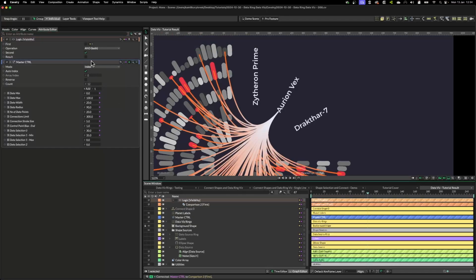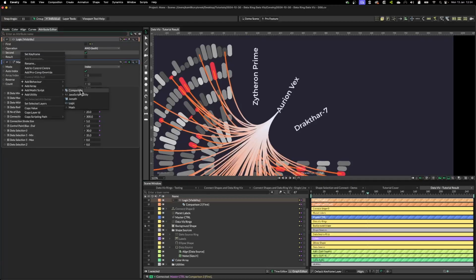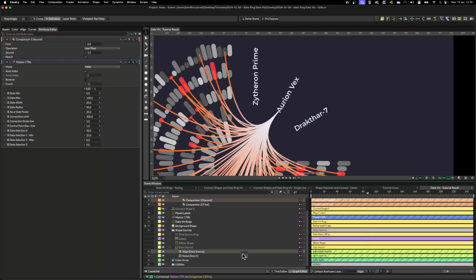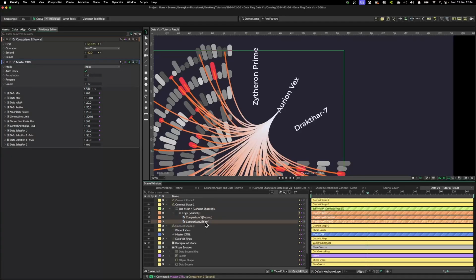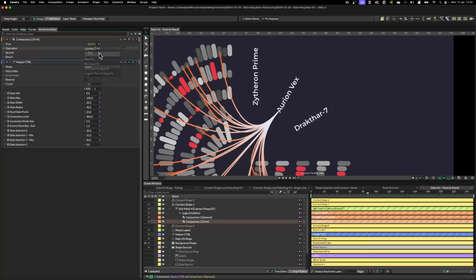Go to logic, and then second operation, math comparison, select it, go to noise, drop it on the first, and this one needs to be, let's say, 40, and drop it here. So let's think about this. So this option is not supposed to be less than, but it should be greater than 35. And the second one, it should be less than.